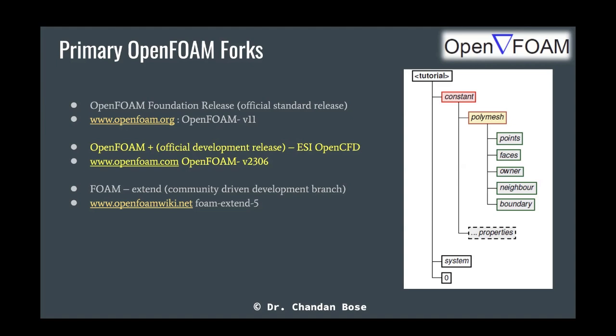Ordinary differential equation. Now, what's the difference between an ordinary differential equation and a partial differential equation? Exactly. So basically, a partial differential equation will have two or more independent variables. And to solve incompressible flow problems, we solve the incompressible Navier-Stokes equation, which is a partial differential equation, and we have time as well as the position vector as the independent variables, and for that reason, we need initial conditions as well as boundary conditions. Is that clear?